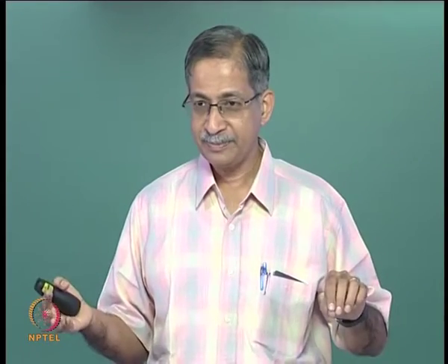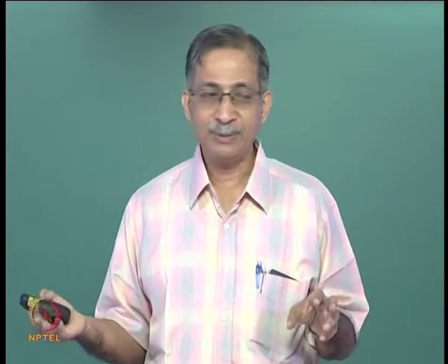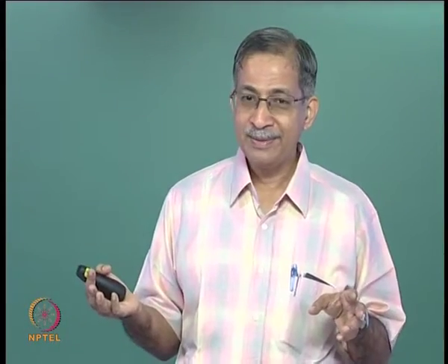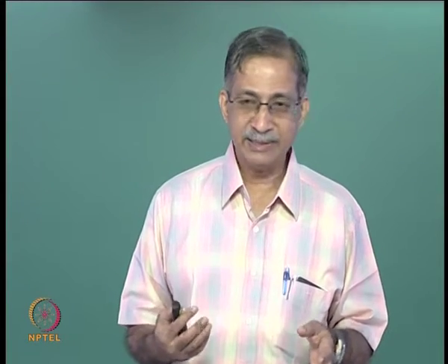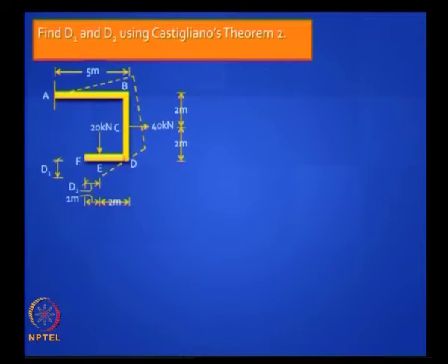By Castigliano's theorem it denotes the displacement at those support locations. Now those supports do not move, so those displacements are 0, and so you can also interpret this as a minimization of strain energy. We will discuss this shortly, that is called the theorem of least work, but let us demonstrate this with a problem.